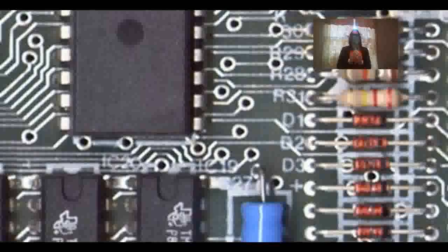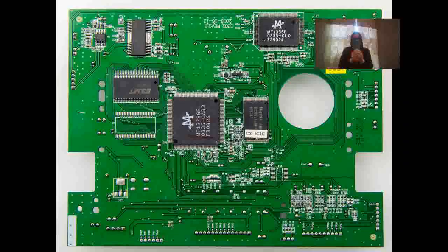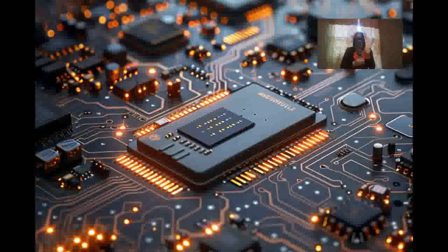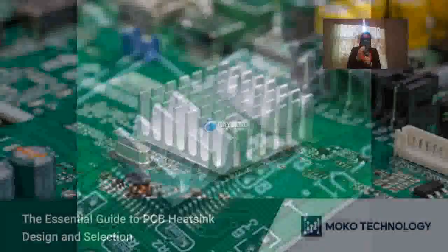Construction of printed circuit boards. A printed circuit board starts out with a thin sheet of copper foil covering the entire surface of an insulating material. If the PCB is to be double-sided, both sides will be covered with a thin sheet of foil. There are a couple of common methods used to produce the circuit design on the foil. The layout of the circuit can be put on the copper using a resistive material. The board is then dipped into an etchant. The etchant removes all of the copper surface not protected by the resistive material.